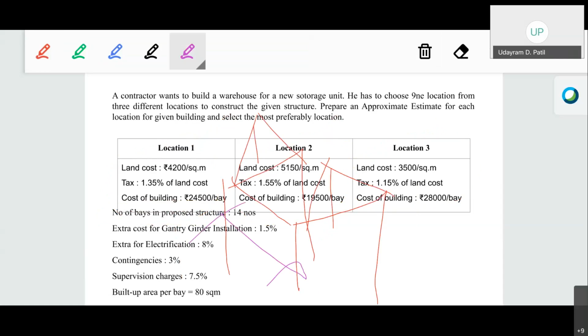two trusses. Okay, in case of an industrial building or industrial estate, if you consider a godown, there are not many walls, it is like one big hall. So in that case, any other service unit is not the most efficient. Therefore we use the distance between the two trusses as a service unit. That particular distance between the two trusses is known as the bay. Okay, that is what we call a bay.